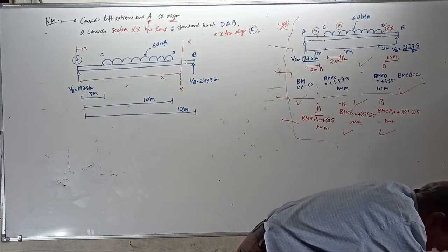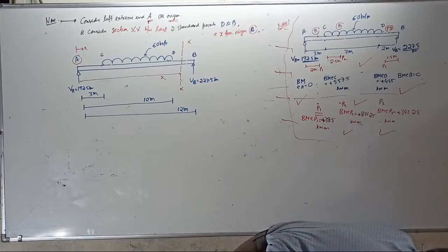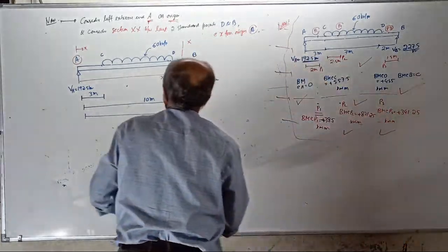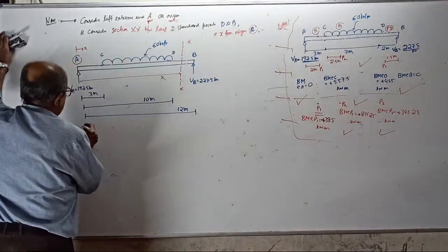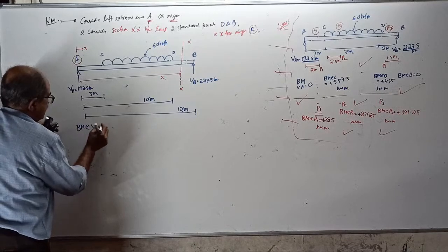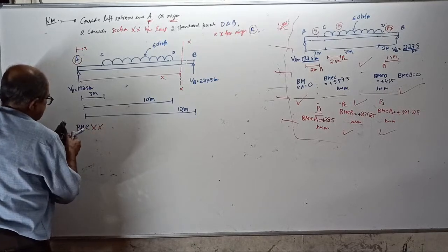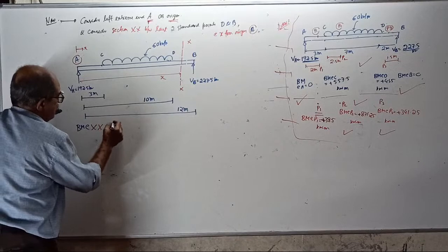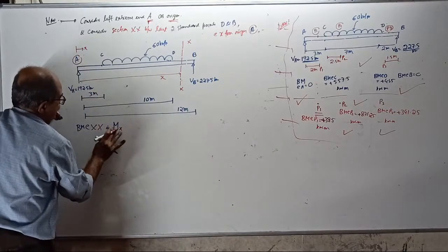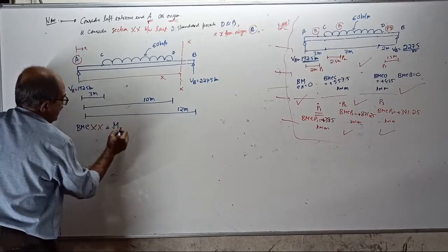3, 10 and 12, systematic way, marking from where? Left hand origin. Yes. Okay. Now, write the equation for bending moment at XX. That is called MX, M at X, with A as origin, sagging positive. See correctly what I am doing.